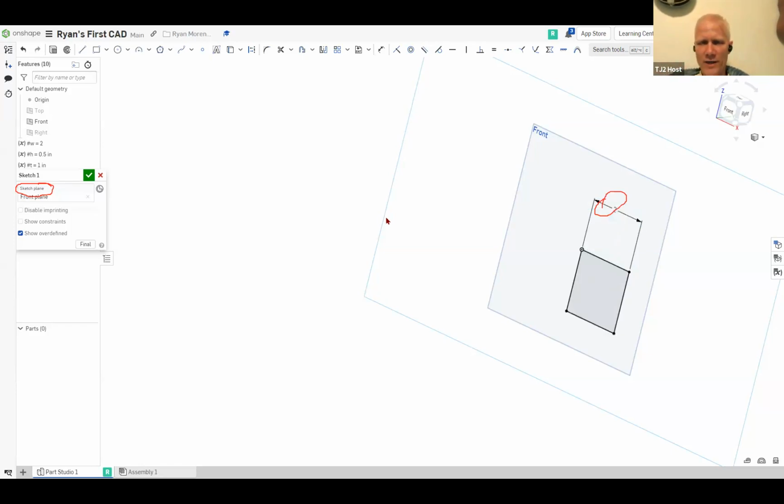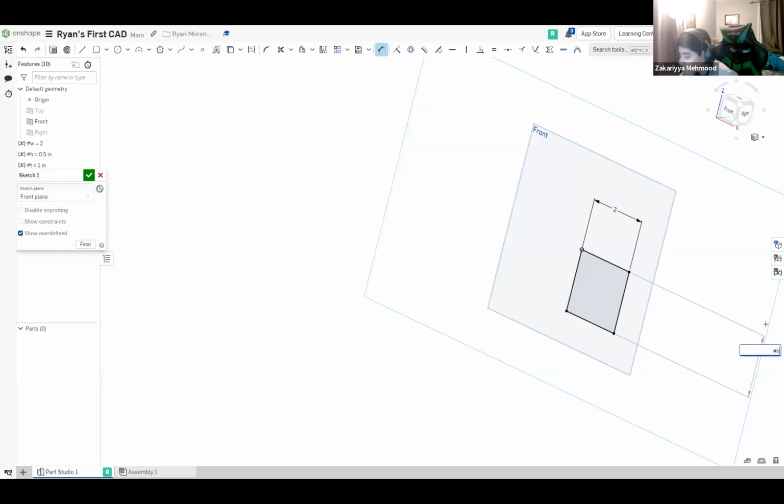All right, now put another dimension on. I'm going to show you something new here. We need a dimension for this one, right? Where's the dimension number? Here it is, right up there. Click, drag it off, click. Okay, now hit equals and choose the height, that's the height we said, right? And then hit enter, and everything's going to go red.